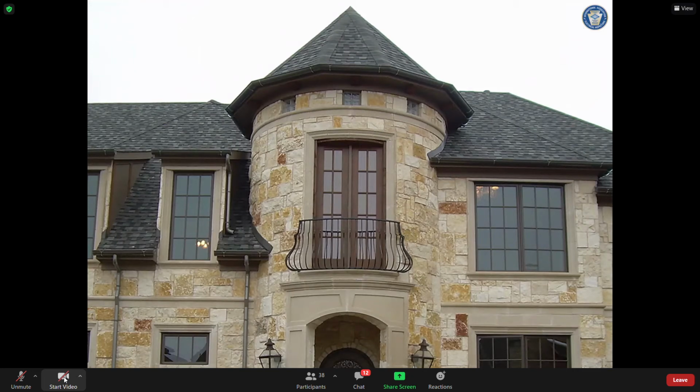What if we had a balcony like this right here, and it was simply there for aesthetics? In other words, these doors do not open to the living quarters. It's just simply there for looks. Am I required to have a receptacle right here? No. Only if it is accessible from living quarters. Now, it doesn't matter what size that balcony is. If those doors are operable, then yes, I would need a receptacle out here somewhere.